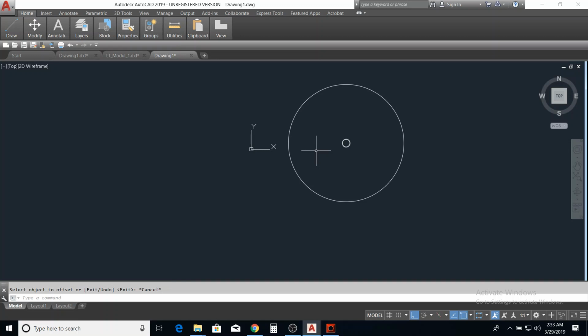In this case, let's consider how many steps. I have a total height of 2,700 divided by 150. That will be 18 steps, which is too many. So I'm going to do 2,700 divided by 180. Then it gives me 15 steps, threads. Some people say steps, but the right word is thread. So it means I'm going to have 15 threads at a rise of 180 mm.